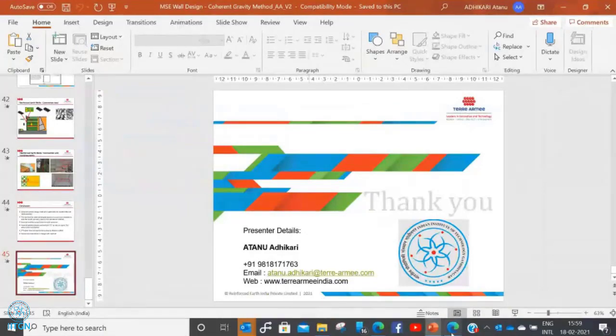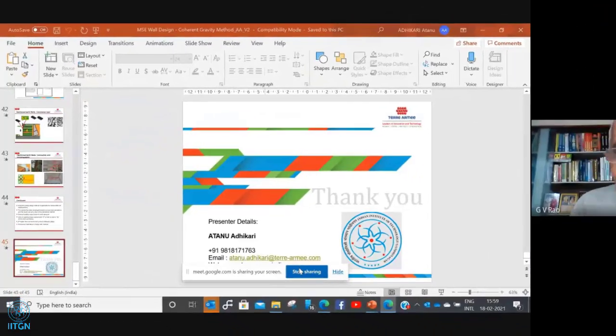Thank you, Atanu. I think it was a wonderful presentation you made. A lot of issues you have taken up and given clarity on, regarding connection strength and also the pull-out. Yesterday we had a lecture by Anil Dikshit, wherein he presented the pull-out values at low normal stress of 50, 100 and 200. And it is very clear to all the students now that the value at 50 kPa normal stress is going to be higher. So when you begin the construction, as you rightly said, the pull-out value is higher. But as you keep going up, that same value is going to come down. That also is a cause for worry for us now.